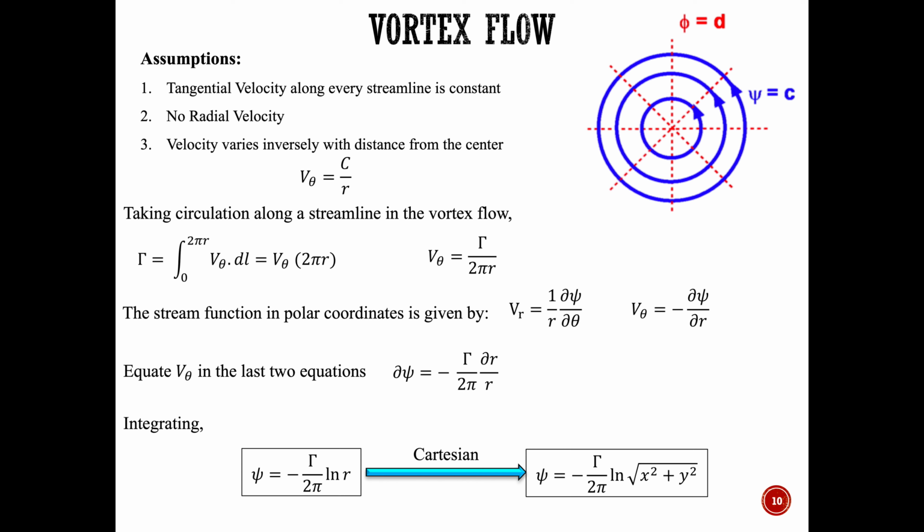So we really need some way to make sure that when we superimpose the vortex flow onto a cylinder, the surface streamline has the same constant value as what you observe when you superimpose free stream plus doublet. Let me show you what that means.